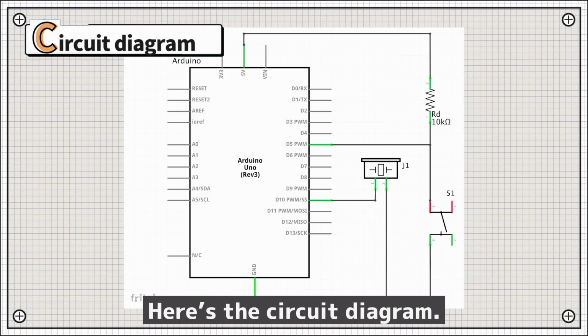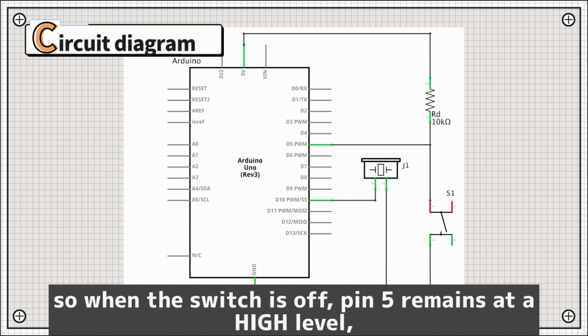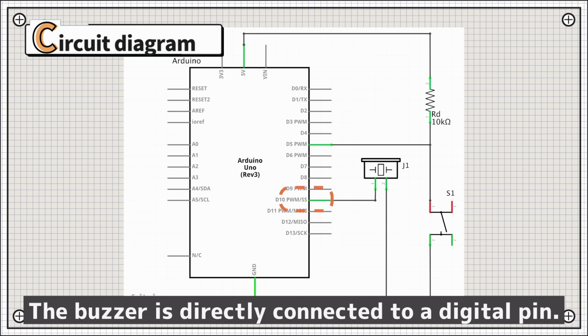Here's the circuit diagram. A pull-up resistor is connected in series with the switch, so when the switch is off, pin 5 remains at a high level, and when the switch is on, it changes to a low level. The buzzer is directly connected to a digital pin.